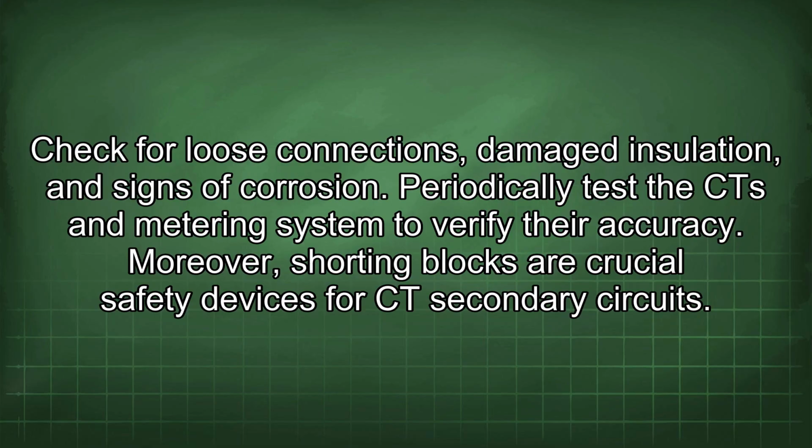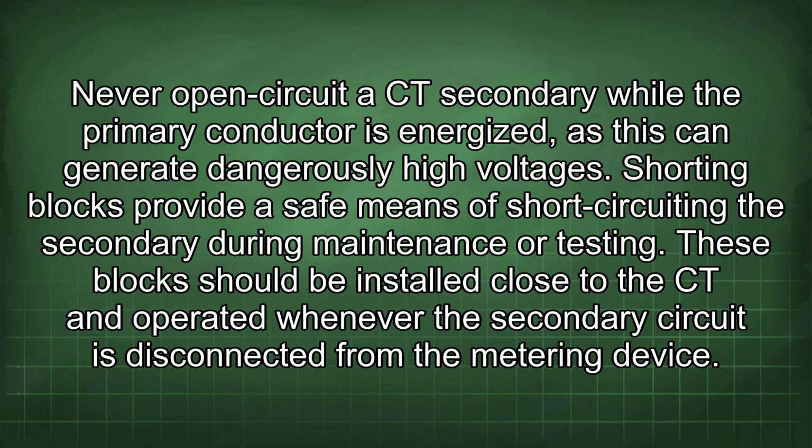Moreover, shorting blocks are crucial safety devices for CT secondary circuits. Never open circuit a CT secondary while the primary conductor is energized, as this can generate dangerously high voltages. Shorting blocks provide a safe means of short-circuiting the secondary during maintenance or testing.